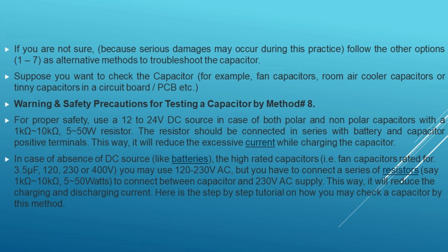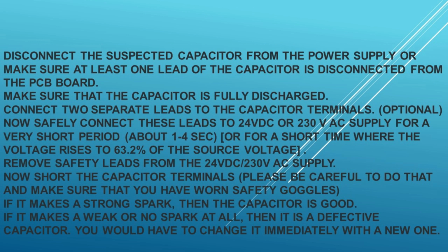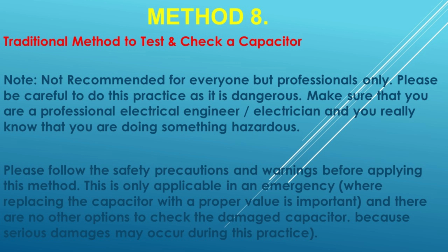This is only applicable in an emergency, where replacing the capacitor with a proper value is important, and there are no other options to check the damaged capacitor, because serious damage may occur during this practice. If you are not sure, follow the other options, 1 to 7, as alternative methods to troubleshoot the capacitor.